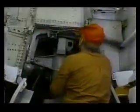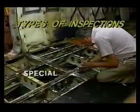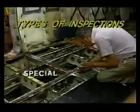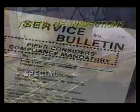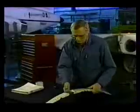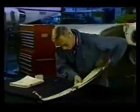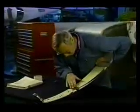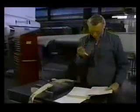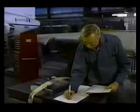You should also examine areas where heavy grease coatings are used as preservatives. If the coating is in question, remove it and inspect the area underneath. Special corrosion inspections are required at each overhaul, routine inspection, or when required by an airworthiness directive or recommended by a manufacturer. When corrosion is found, the quality control inspector makes an evaluation to determine the extent and types of damage sustained, and then recommends a course of corrective action. The results of every corrosion inspection should then be recorded for later analysis.